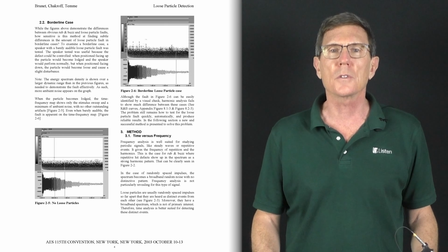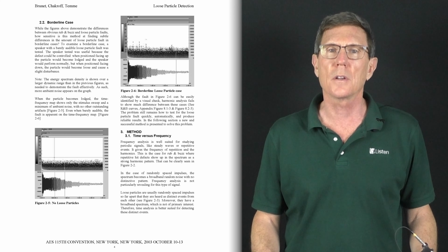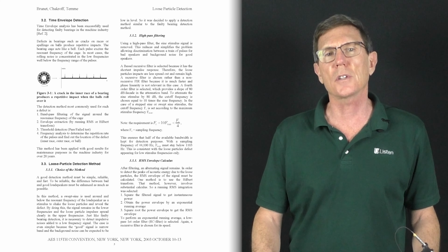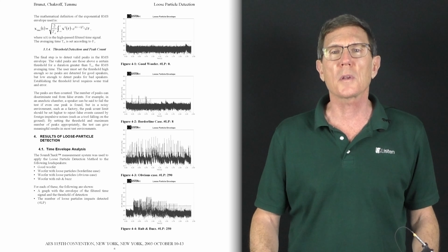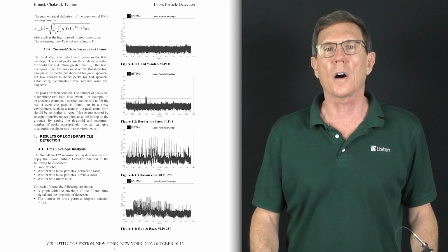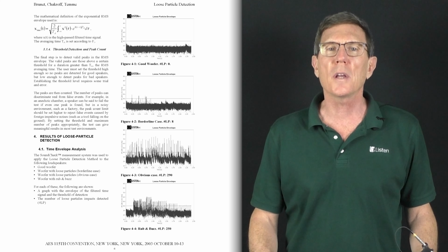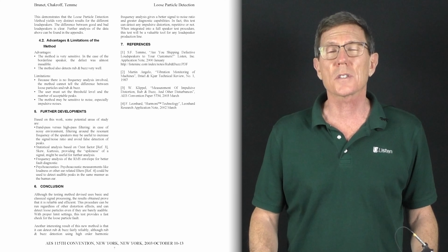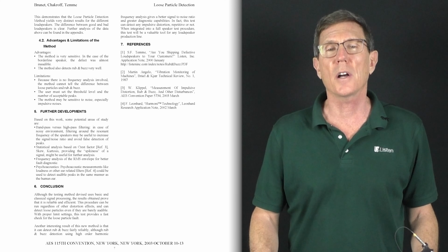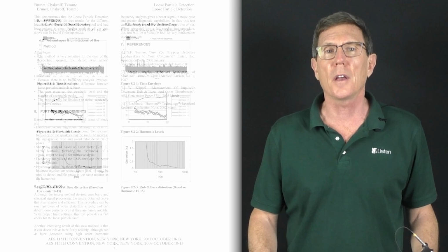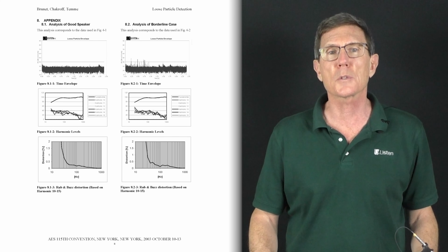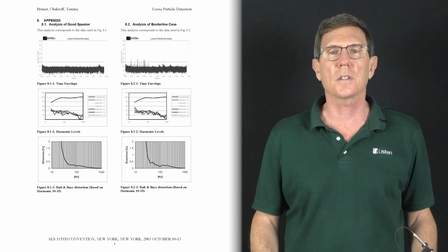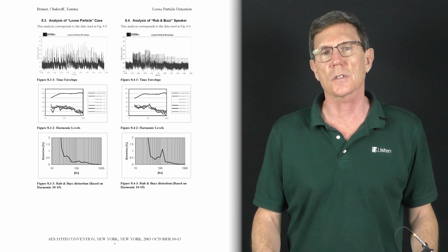This early model used a time envelope analysis method, which is widely used for detecting faulty bearings and gears in the machine industry. We were the first people to use this technique for audio quality measurements, and we made several adaptations for this new application. We used a sine sweep stimulus and then applied a tracking high-pass filter and RMS envelope analysis to the response waveform. Within this envelope, we then detected and counted the number of transient events.